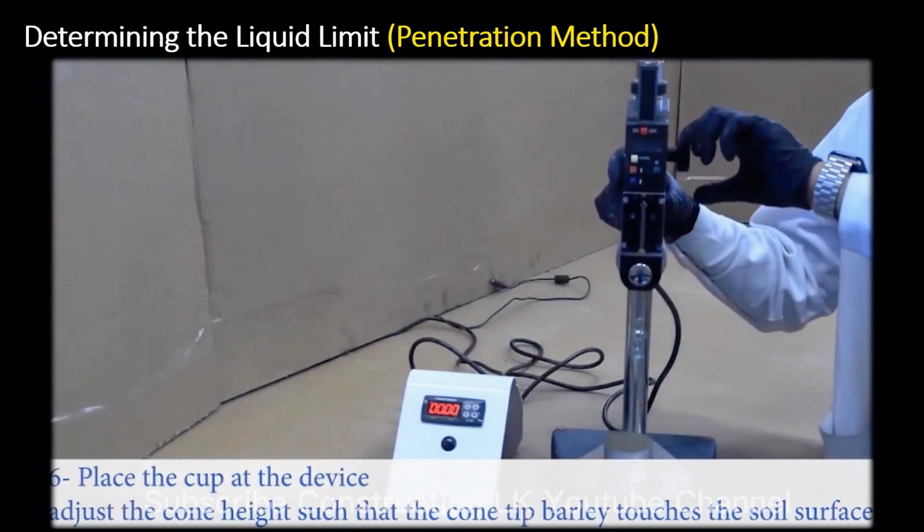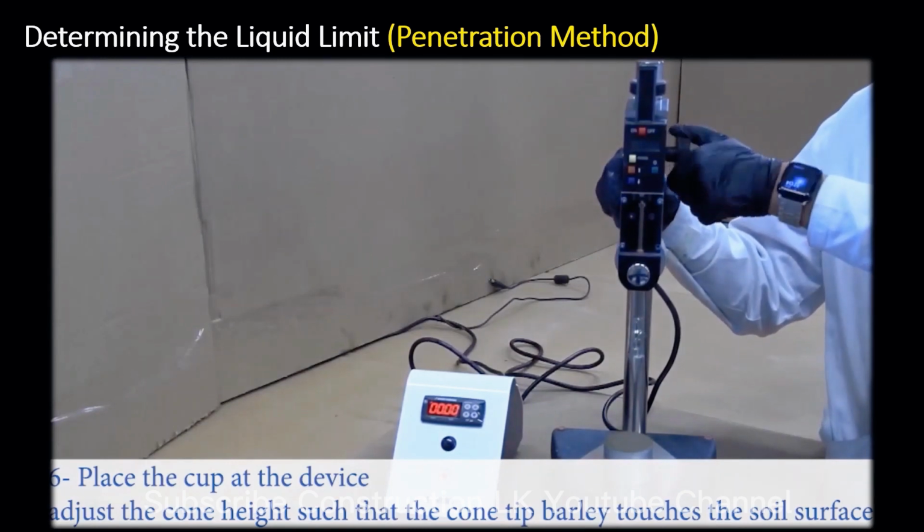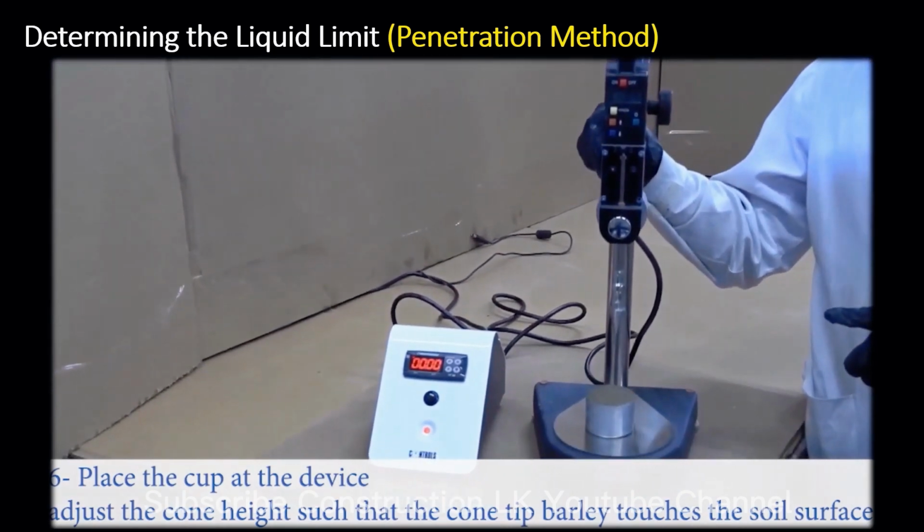Then the specimen is placed in the penetrometer and the cone is lowered, so that it just touches the surface of the soil in the cup. The cone should be locked in its support at this stage.